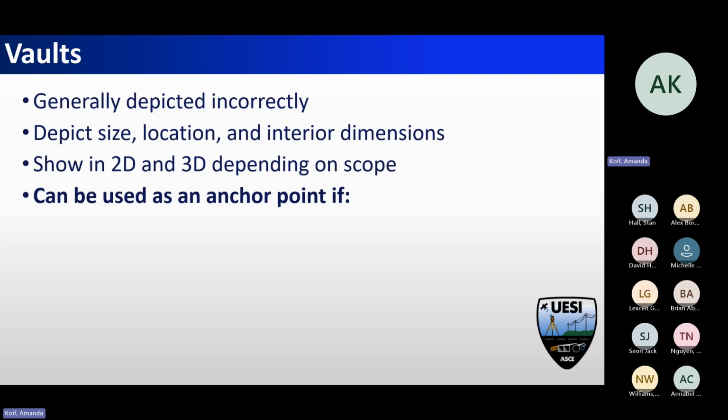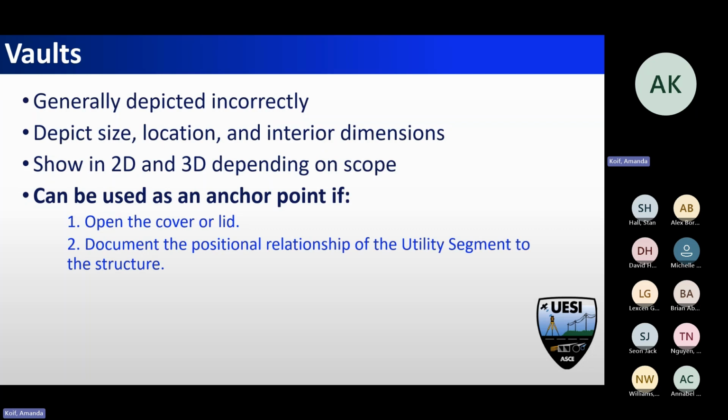Can those be used as anchor points? Sometimes. If you open the lid and you validate that that's maybe at the center, or you've got some kind of way to show that at exactly that point, you can draw a line from it, then you can use it. But if you don't open that lid, then you're going to make the bad assumption like before.